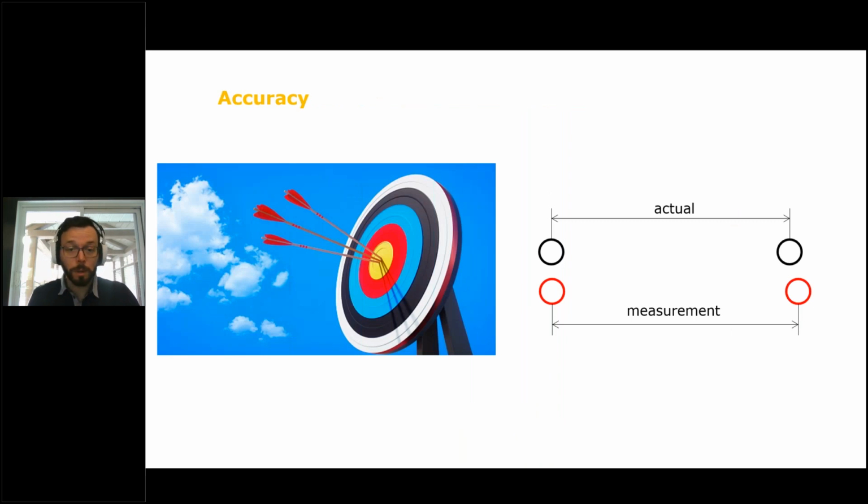Now, the accuracy refers to the error in measurement of the part versus the actual scan. As an example, the more accurate a 3D scan is, the more likely that the part designed with that scan as a reference will fit into your assembly. Think of a simple example: a distance between two holes, for instance. If you're 100 microns off or 4,000ths, well, it's not so bad. But if you're a centimeter off or 3/8, then it's not so good.